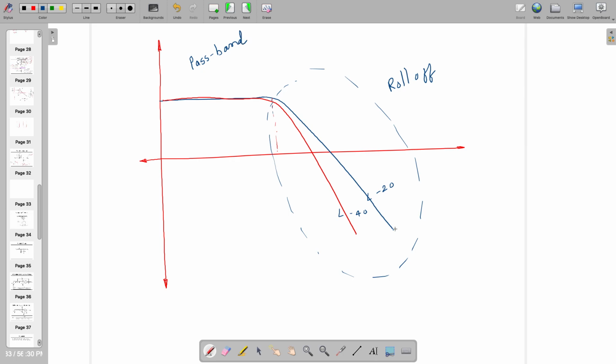Sometimes you are going to make a circuit which has such kind of response, meaning you will have some extra zeros afterwards so that it will become flat. Then you are going to call this particular part of the magnitude response the stop band.